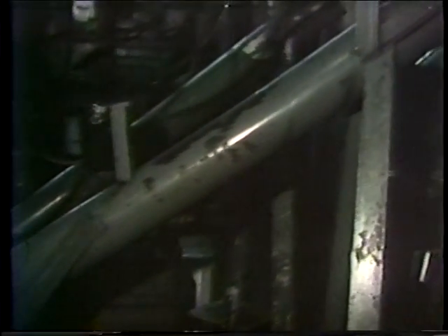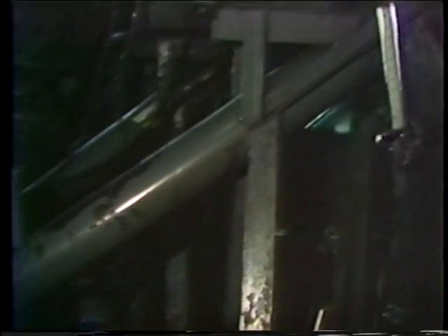One thing which should be taken into consideration: if possible, we want the conveyor drive mounted on the discharge end, so the shaft itself, which tends to be limber, will be in tension, and the bearings in the reducer can be used to absorb this thrust. Like the conveyor belts, the screw conveyor may be horizontal or inclined, and more recently, there are a number of applications where it is actually vertical and used in place of an elevator. This application is frequently found in the grain and feed industries.